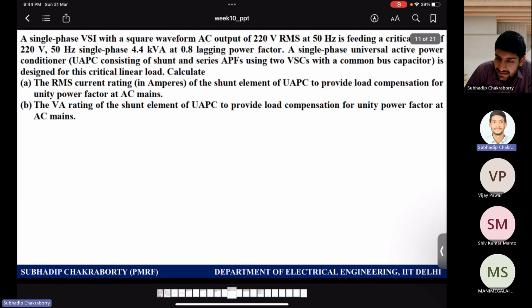You get my point? Such that we are not penalized, because for our fault if we draw non-linear currents from the supply, we should not be penalized for that. That's why we make shunt arrangements to mitigate those harmonic components. So current quality we always want to improve at the supply side. Voltage quality we always want to improve at the point of common coupling where the loads are connected, for sensitive load operations, such that malfunction of the sensitive loads or motor based rotational loads does not happen. So you understand the point, right? Why we use those, both are required during those disturbances, right?